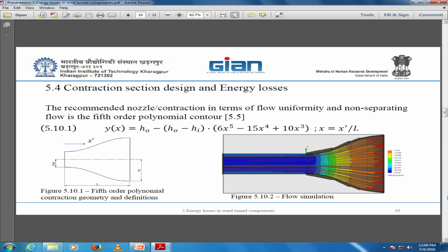It's really fairly downstream. You see our Reynolds numbers starting with laminar, but very fast they'll move on to turbulent. So in the diffuser it will be turbulent. It's better to be on the safe side, I mean, to assume that you are turbulent there, in terms of calculations.